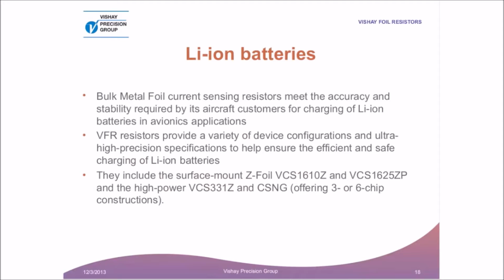Lithium-ion battery chargers require accurate current and voltage settings and monitoring, as well as a constant current and constant voltage. If these requirements are not met, the charger will undercharge or overcharge the battery. A failure to completely charge the battery results in reduced battery life, while overcharging can cause batteries to fail due to overheating.